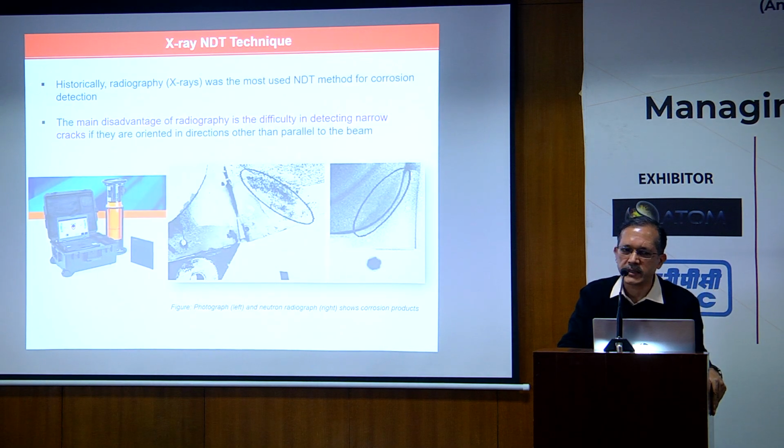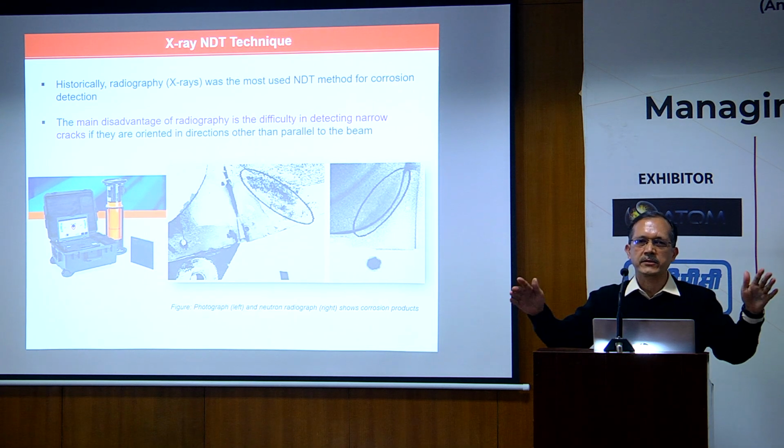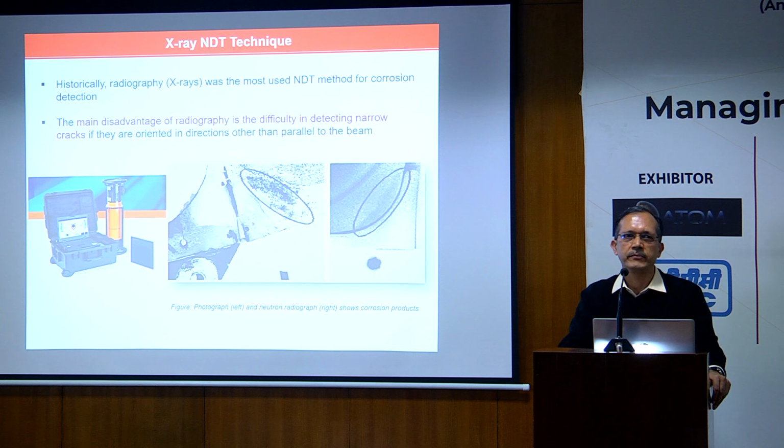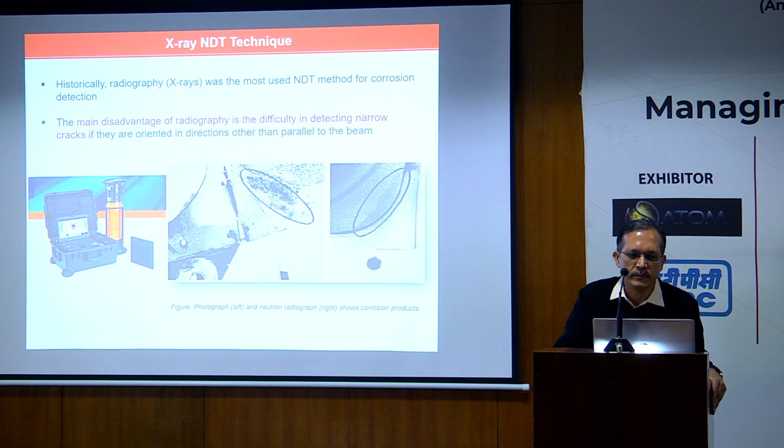The same is the case with the X-ray NDT, which is also known as the radiography technique, even though it has been widely used in the aircraft industry. And here also the problem is that minute cracks, of the tune of say a width of a few microns or a depth of say a few millimeters, cannot be detected using this particular technology.